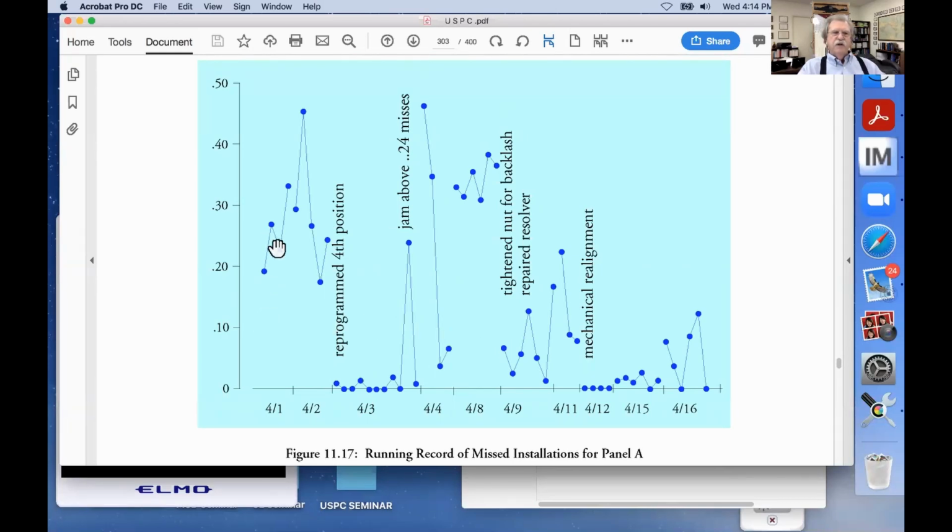Each dot here is 1 sheet of paper, which is what, 10 minutes elapsed time? And some of these are consecutive. So 4.3 tells you the process is capable of virtually perfect operation. And all the other days show you they don't know how to maintain the robots. I mean, one of the problems is drop nuts. The nut would drop off before it got to the part. Well, they weren't cleaning out the filter on the vacuum system except once a week.